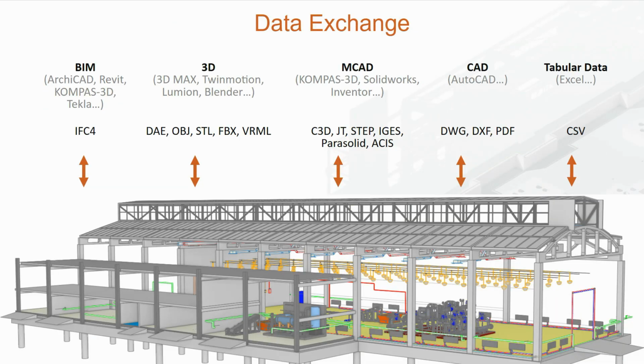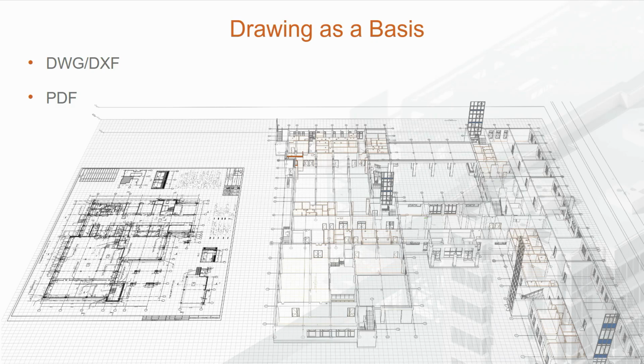We understand that, when working on a project, specialists may use different tools to solve specific tasks. To avoid problems with exchanging data between all the programs used, you can import and export the Renga model in a wide range of formats. Solid file formats such as JT, STEP, Parasolid, and IFC for the Open BIM approach. The ability to import and export in DWG and DXF formats helps you to interact with other CAD systems. You can also import DWG, DXF or vector PDF data into a drawing or insert it as an underlay in the 3D view.